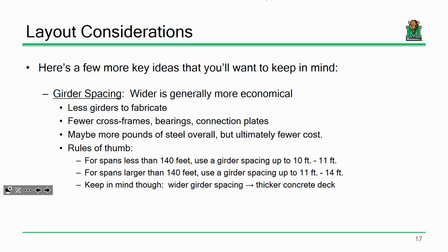That's a good question, and that's a topic of debate. Some people do and some people don't. People think 2 girders are fracture critical, 4 girders aren't. Well, where's 3? I've asked that question to different bridge engineers, and I get a different answer every time. As soon as people start talking about it, they say, well, I'm just going to use 4 girders, and then I don't have to worry about it.